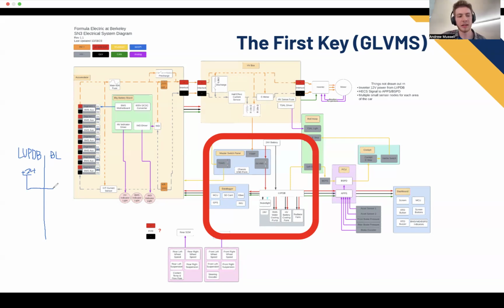And this goes out to the brake light. The brake light isn't just one LED. It'll be an array of LEDs in parallel, but for our purposes, I'm just going to draw one so you get the general idea. So we have that LED, and then it goes back into here. The way we have this set up is a MOSFET to ground, and then this gate goes to an STM32 pin.